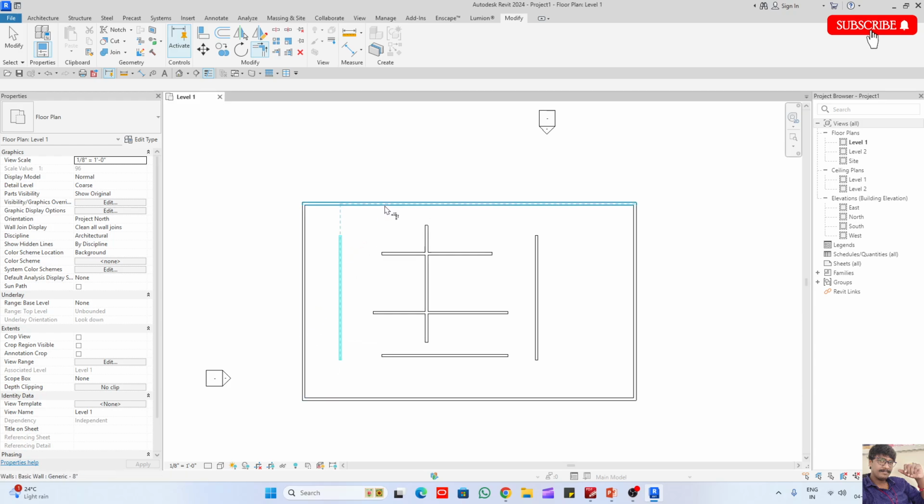If I click this wall, which extends, which trims? There are two walls, horizontal wall and vertical wall. Yes, that's it. Vertical wall will extend, horizontal wall will trim. That's what you have to say. But I want to only extend, I don't want to trim this one. So corner will not be useful now. I want to extend this wall here, this wall here, this wall here, but I don't want to trim the horizontal wall.